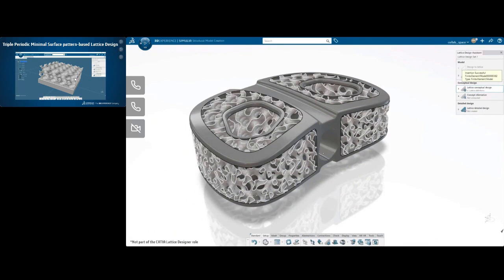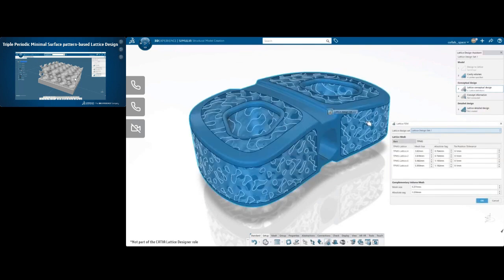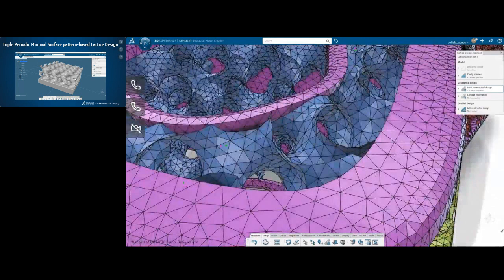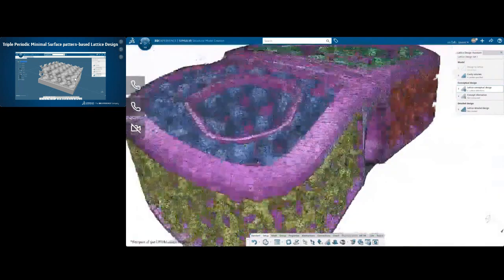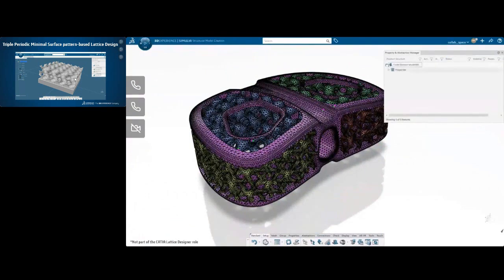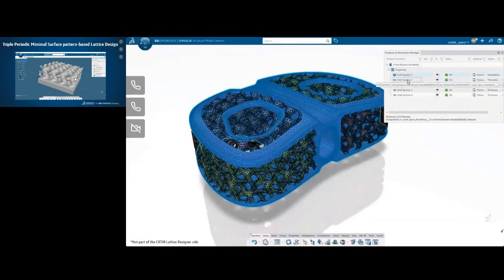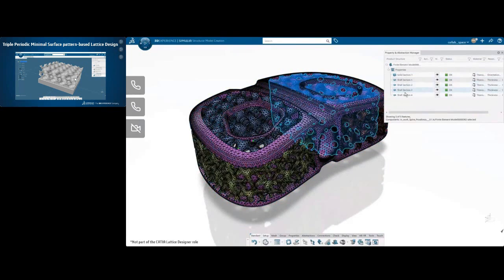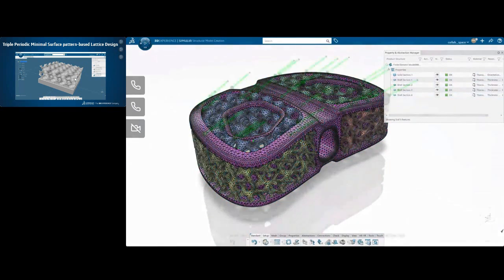Now I go to my finite element analysis application on 3DEXPERIENCE, and I will want to run a simulation. Before that, I will create my finite element model. In this case, not like in the first or second video, we will not use tetrahedral mesh on the explicit tessellated representation, but we still use the light representation. And 3DEXPERIENCE is smart enough to create automatically a shell mesh for the lattice, the TPMS, and a tetrahedral mesh for the outer body.